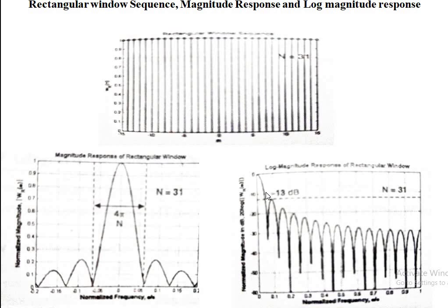The approximated filter response actually differs from the ideal desired response in several ways. There is a sharp transition in the ideal response at omega equal to omega c, but here we see a gradual transition, and in the pass band a series of overshoots as well as undershoots also occur. In the stop band the ideal desired response is 0, but the FIR filter has a non-zero response, and this is what we call leakage.